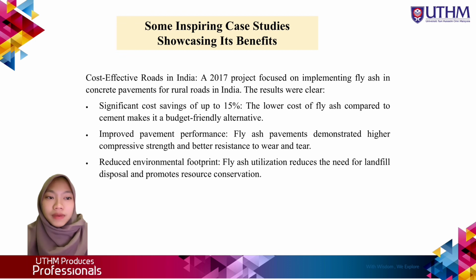So next is cost-effective roads in India. A 2017 project focused on implementing fly ash in concrete pavement for rural roads in India, and the results were clear: a significant cost saving of up to 50%, and the lower cost of fly ash compared to cement makes it a budget-friendly alternative. And we can improve pavement performance, and fly ash pavement demonstrates higher compressive strength and better resistance to wear and tear, and reduces environmental footprint. Fly ash utilization reduces the need for landfill disposal and promotes resource conservation.